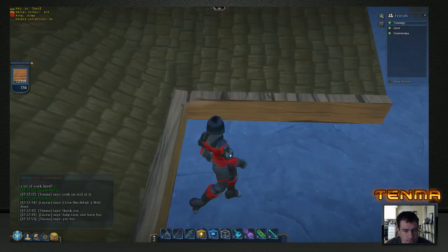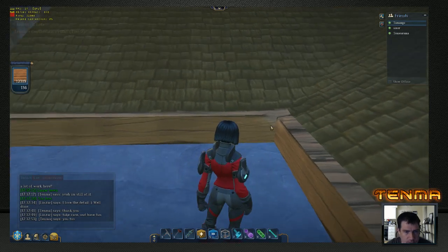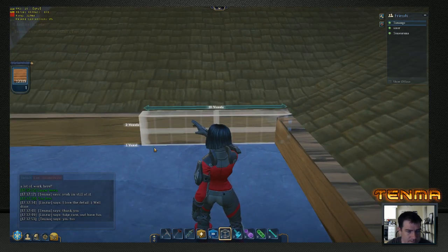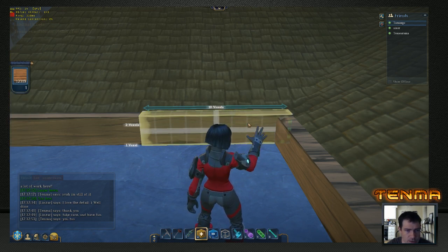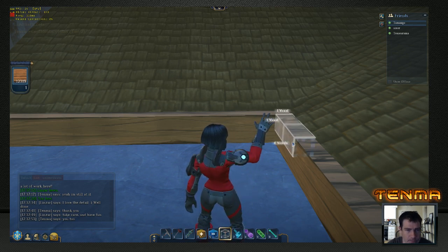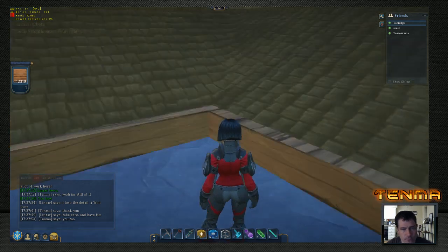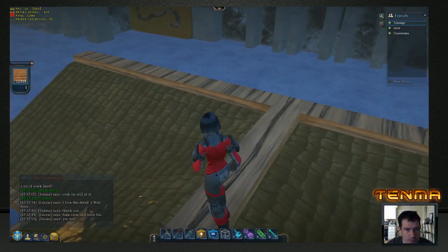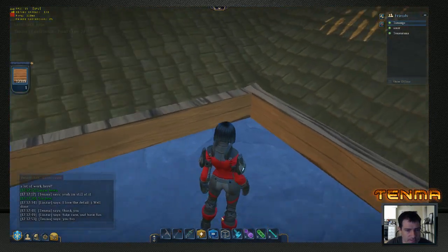Now I hit this right here with my smooth tool, so we'll select that area, and I'll take that same texture and use my add tool on that selected area to straighten it back up. And that solves that little touching area that I shouldn't have hit.